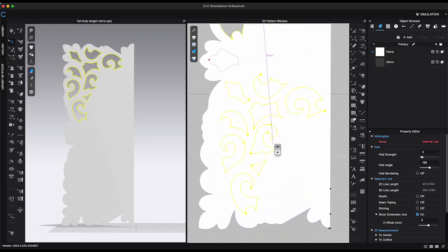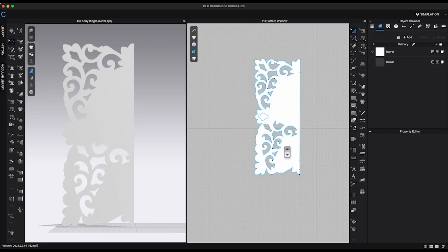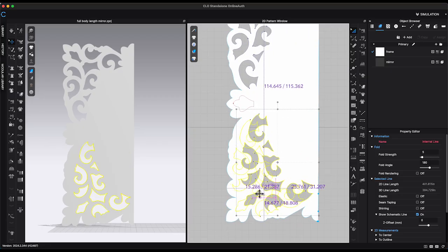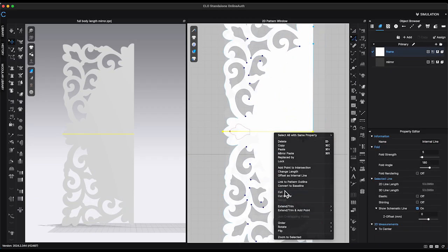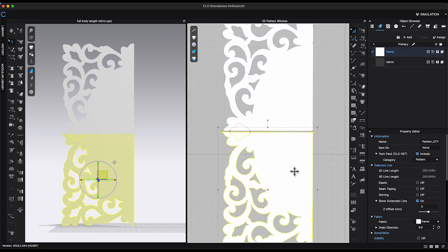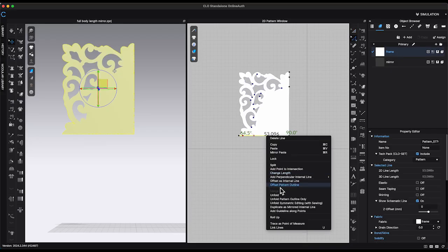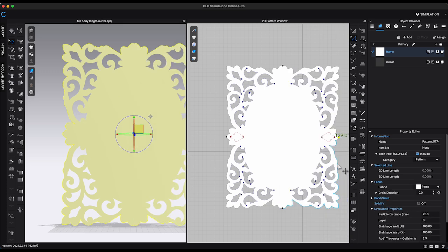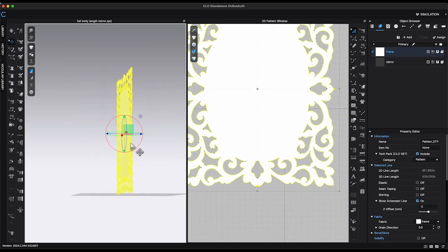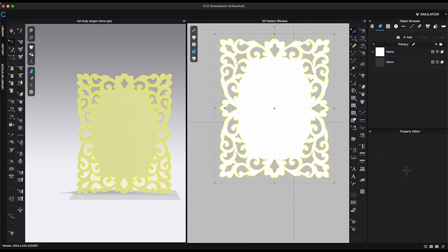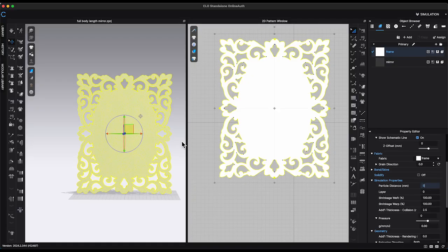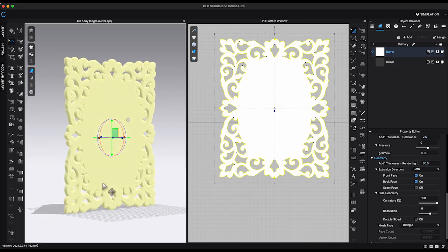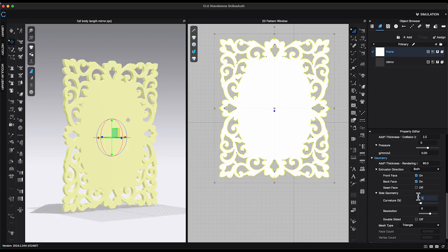Since the cutout detail repeats across all four corners of the frame, you can either copy, paste, and flip the shapes for each corner, or use the Unfold function for faster mirror duplication. Lower particle distance to 5 and add thickness rendering to the pattern. Decrease curvature percentage to get cleaner cutout edges.